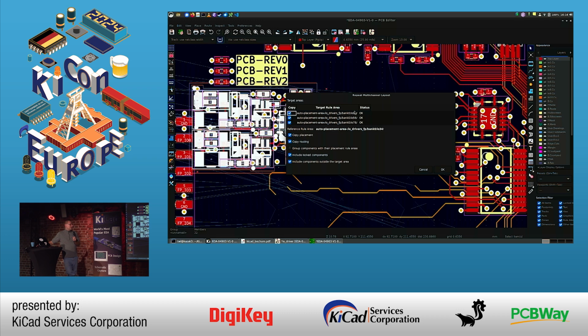What does it mean that they are compatible? That they have the same connection topology and the same footprints. They need not be in different hierarchical sheets in the first place, although this is the preferred way to go, because for complex multichannel stuff, hierarchical sheet instances are generally a comfortable way of managing the complexity, right?